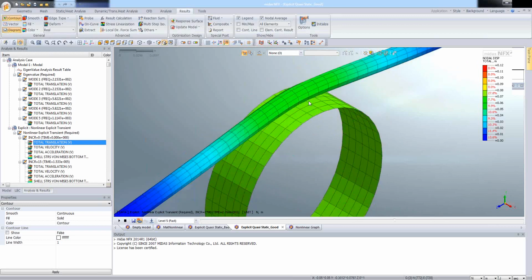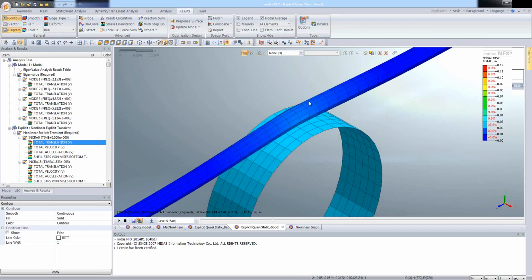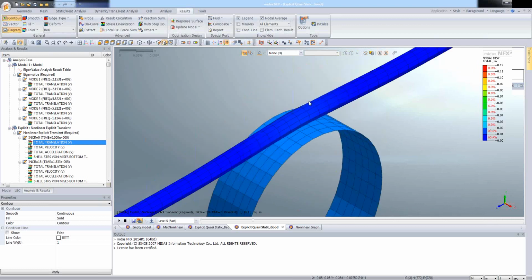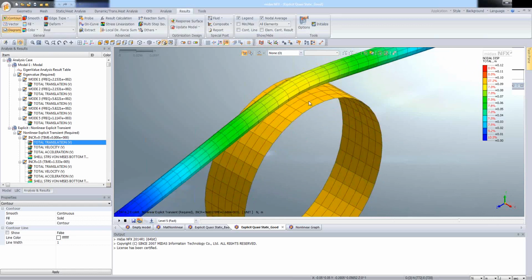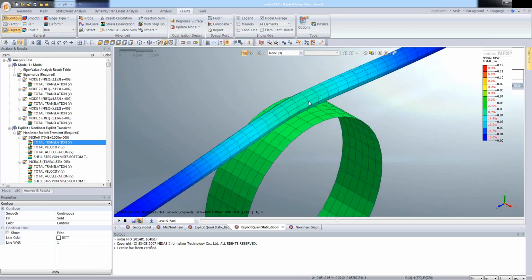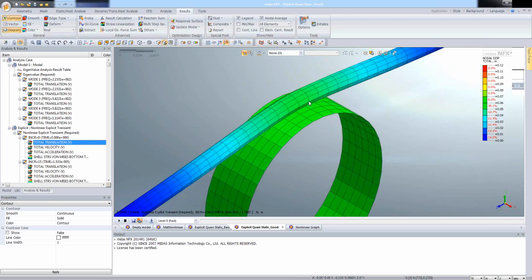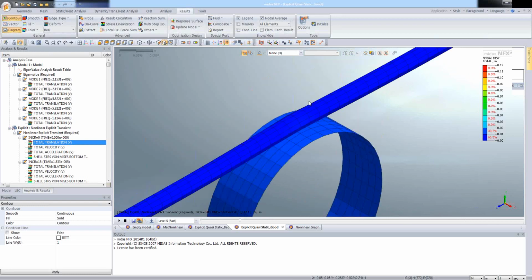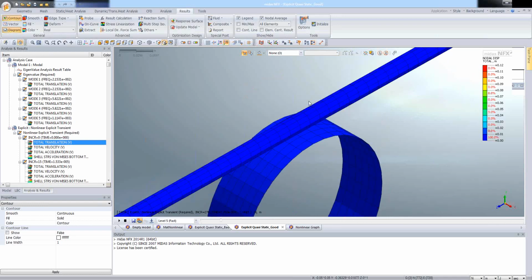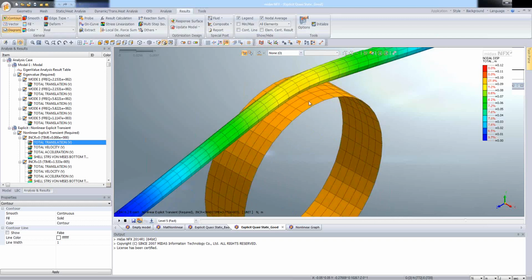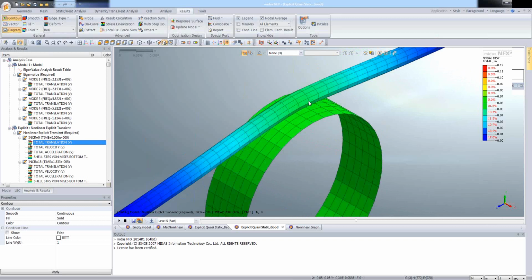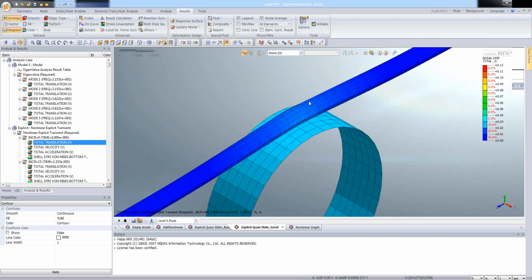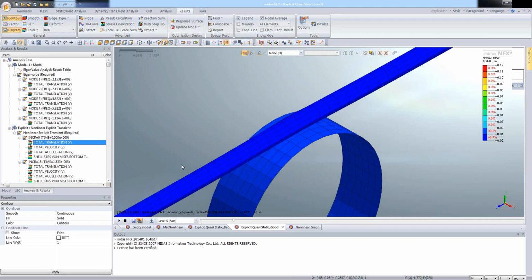To the end, I just want to say a few things about the suggested approach. When you want to perform quasi-static simulations via explicit, you can run a series of simulations in order from the fastest load rate to the slowest, and you also have to perform many simulations to get a proper understanding of the effects of varying the model. So that's all for today about the examples.